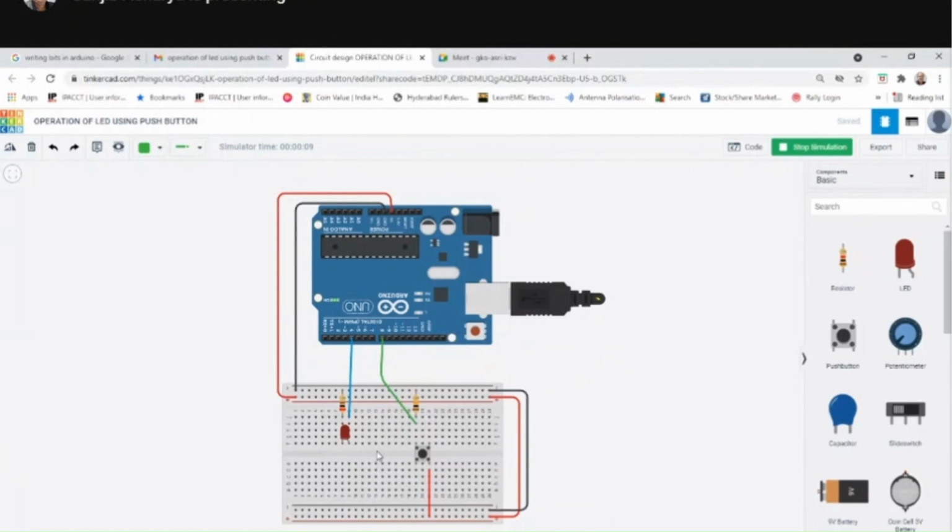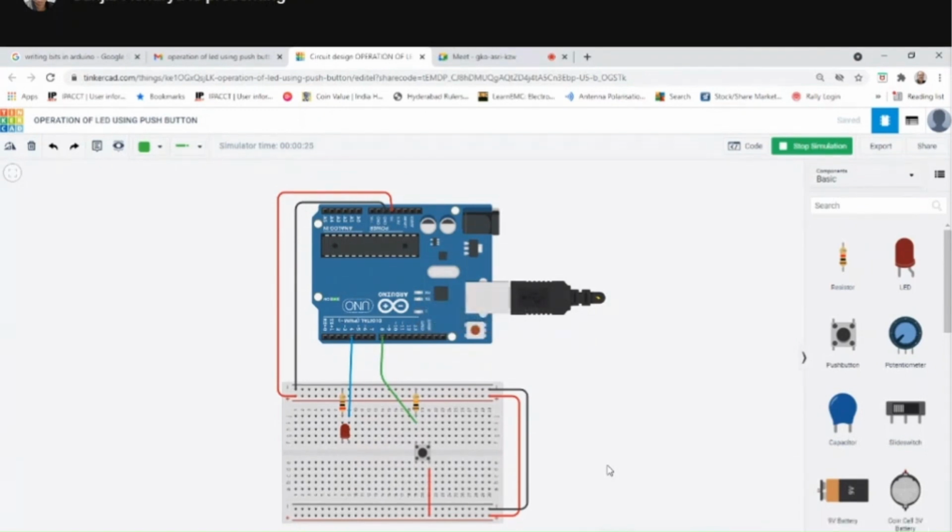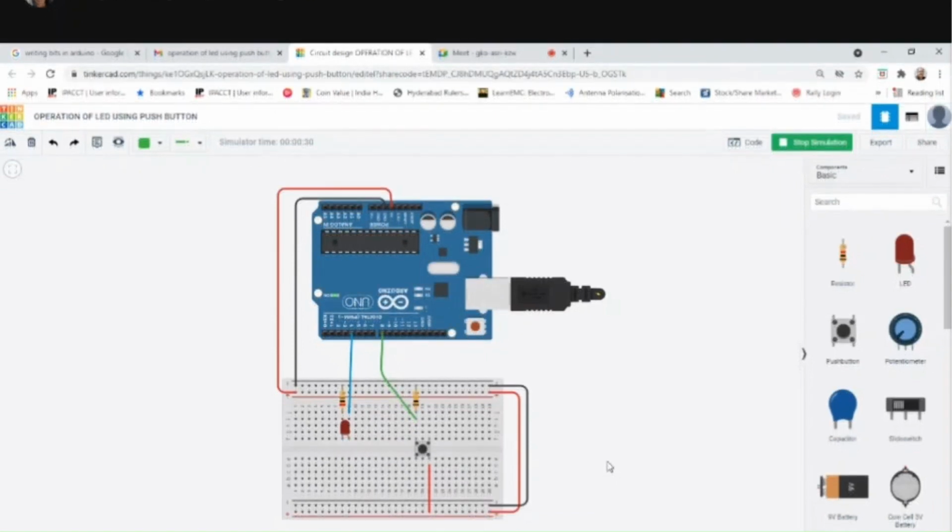on only once. Yeah, the requirement was that after the button is pressed and released, it has to turn on and will remain on for 2 seconds. Now, if I press multiple times, still the LED will turn on after 2 seconds because it is ignoring all those on-off transitions. It is just taking one on to off transition and then waiting for 2 seconds, and in those 2 seconds, whatever it finds, it filters out basically, right? So that's the program. So that's okay.